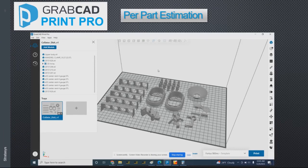So this first tool we're going to talk about is per part estimation. In the past, if you were quoting parts and needed to know what the runtime and material consumption were for parts from different customers, you'd have to process them individually, because GrabCAD Print would only give you the total runtime and consumption for the entire tray of parts. So if you needed to know what an individual part is, you could only have that part on the platform when you did the estimate. Now we can batch process those, so it's a huge time saver.